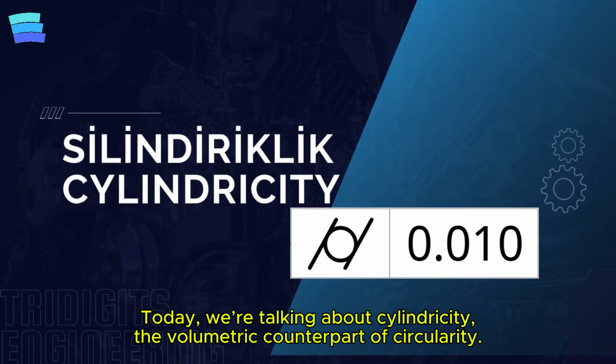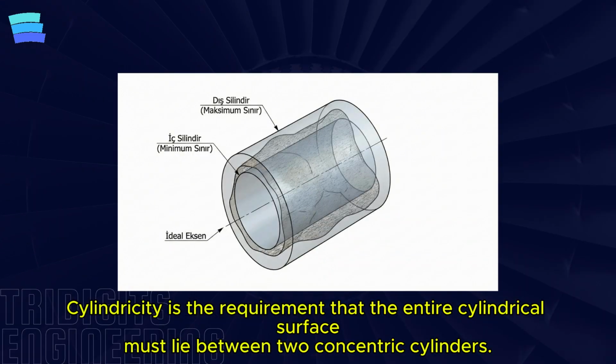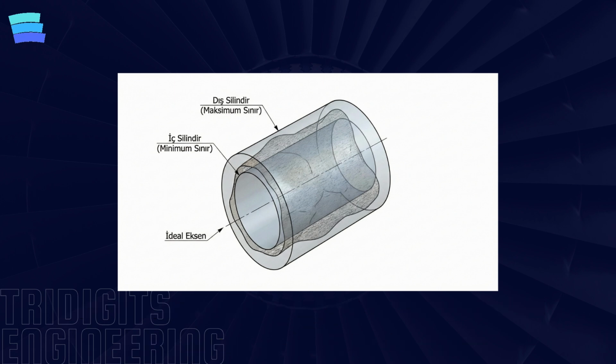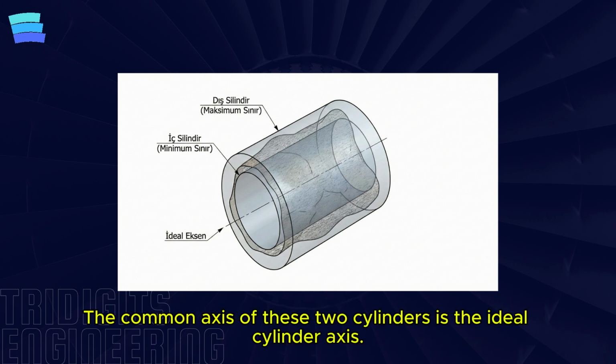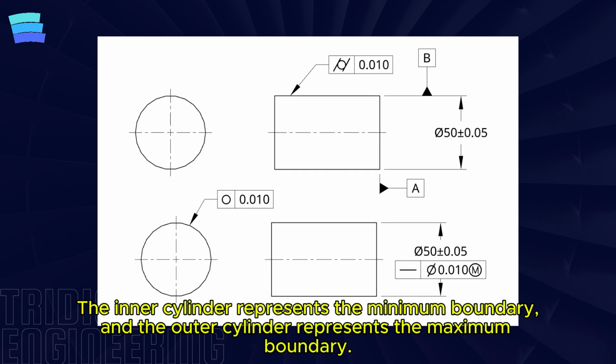Today, we're talking about cylindricity, the volumetric counterpart of circularity. Cylindricity is the requirement that the entire cylindrical surface must lie between two concentric cylinders. The common axis of these two cylinders is the ideal cylinder axis. The inner cylinder represents the minimum boundary, and the outer cylinder represents the maximum boundary.